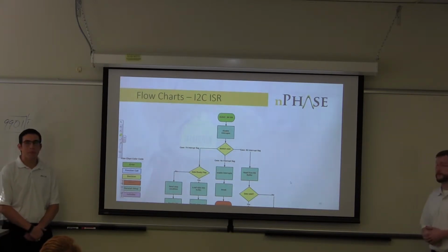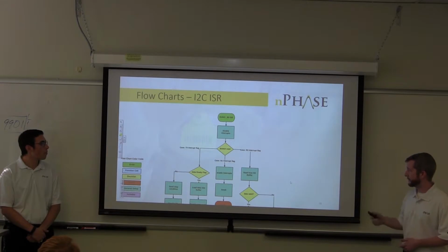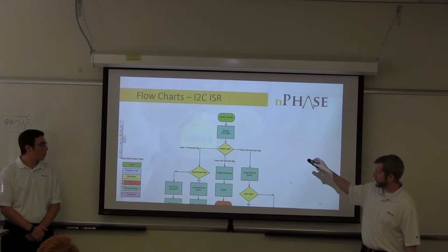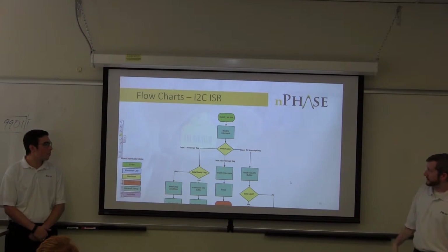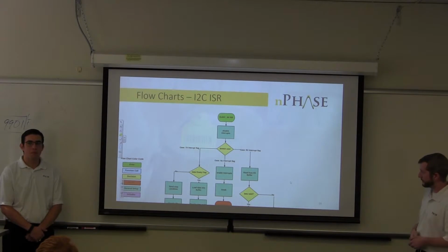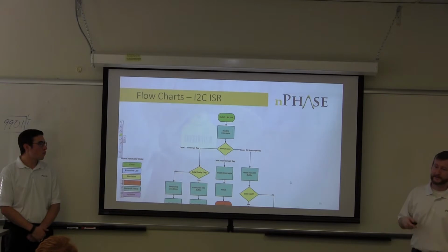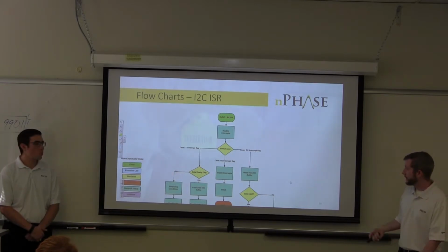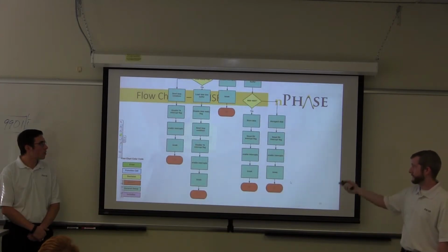Here's our I2C interrupt service routine. This is what's going to be controlling those communications that we were just talking about. Right away, we disable interrupts to prevent it from getting interrupted in the middle, and go into a switch case. Just to cover this real quick, if somehow it gets in here and there's no flag, it just re-enables and breaks out. If the TX interrupt is flagged, meaning that we've initiated I2C communications, it checks to see that the data ready flag is there. That means we have data that's actually trying to go into the TX buffer. If there's not, then we simply send the stop condition, the stop I2C, disable the interrupts, reset, and break.